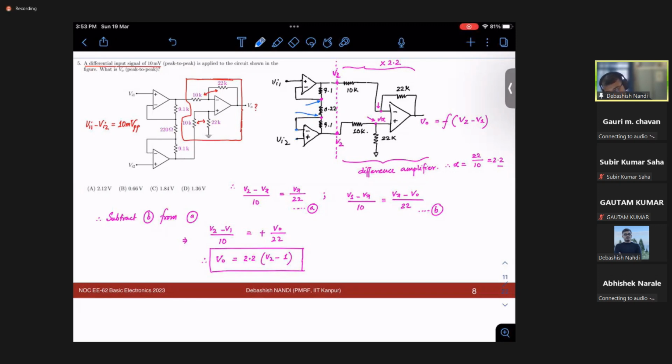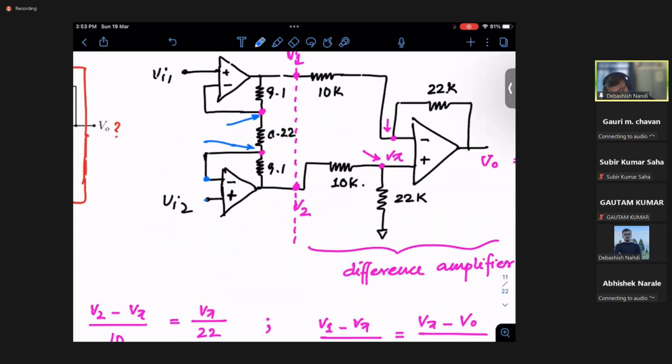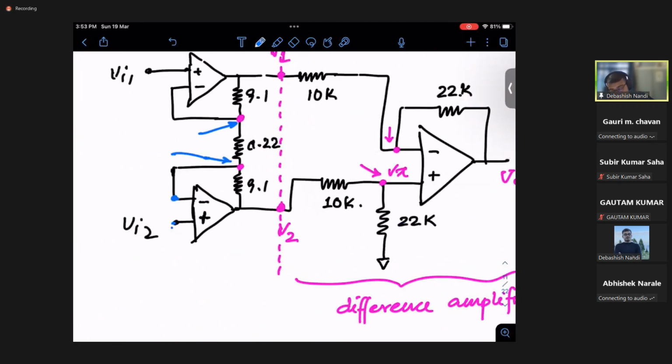This is just connected directly here, so this is my V2. Similarly, this is V1. Virtual short will be there because this is connected through negative feedback and the op-amp is ideal. This point I am reiterating every time to make sure that you keep in mind, these are the essential conditions for virtual short consideration. This we have discussed in detail in last session.